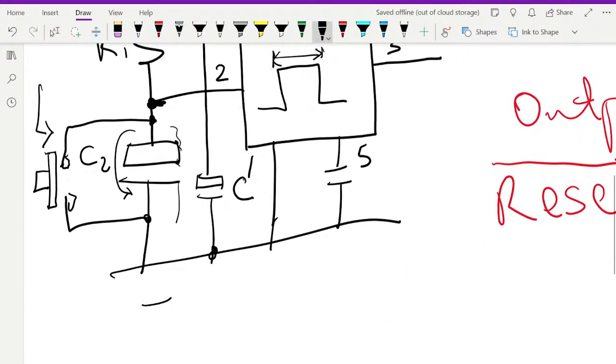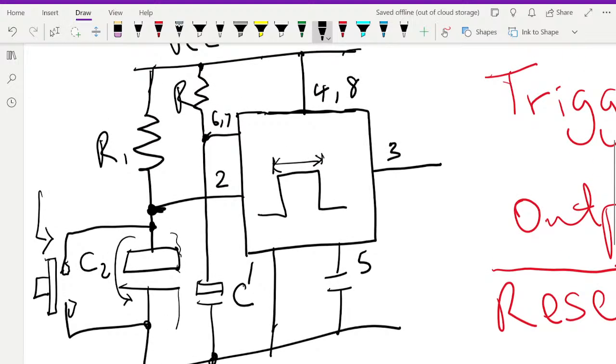So my monostable period is the same as 1.1 RC, where R is, again, let me use a different color to highlight it, this R, and your C is this C. Not the first ones, I'm going to put a cross, but not because we're canceling it out, but we are not referring to this.